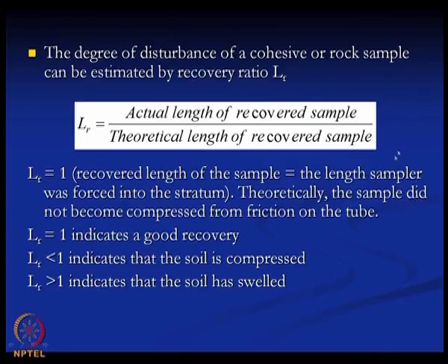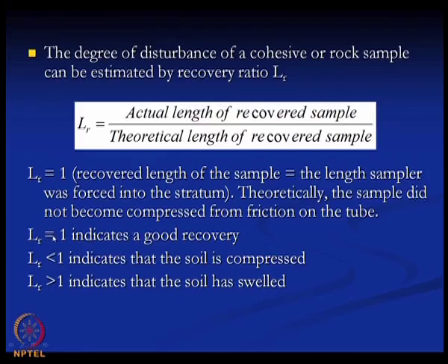If the length of the soil sample we have collected is equal to the length of the sampler that we have pushed into the soil to collect the sample, then the LR ratio will be 1, and LR equal to 1 indicates a good recovery.